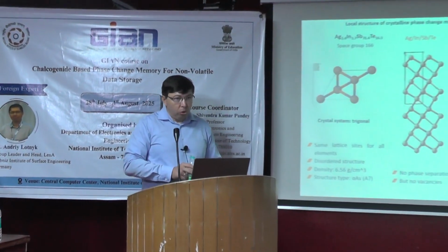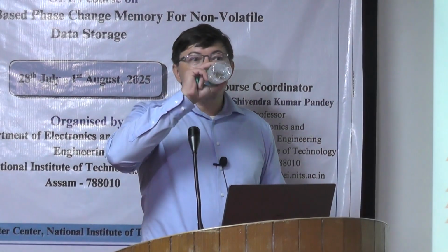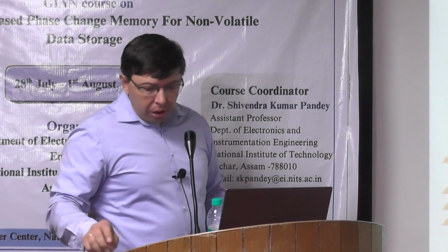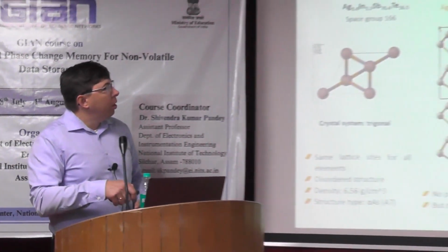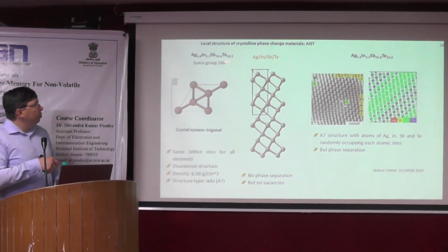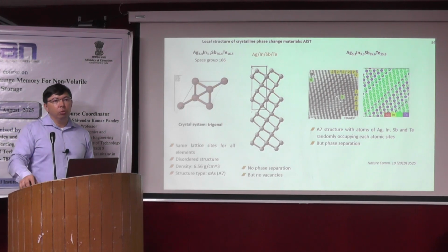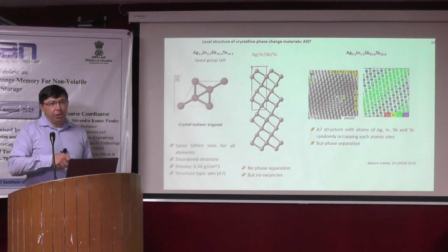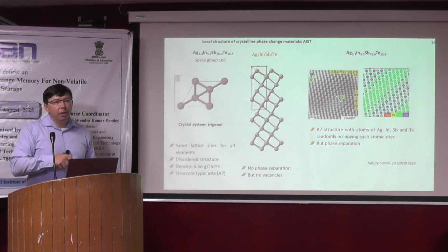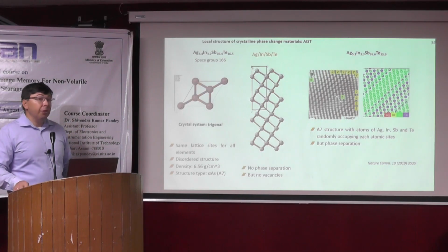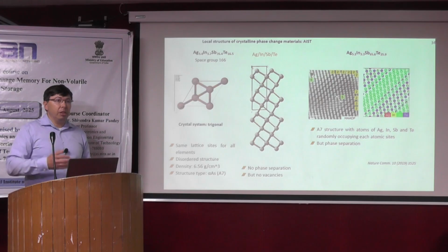Tellurium, yeah, it also depends on the composition. As you can see here, I don't know what was your composition, but it's a little bit different. But they found this segregation of antimony. In your case, it can be tellurium. Did you use also AST? No. GeTe with arsenic, tin. Tin. Okay. Yeah, it's a different system and a different crystallization kinetics. So it can bring you to the formation of tellurium precipitates.